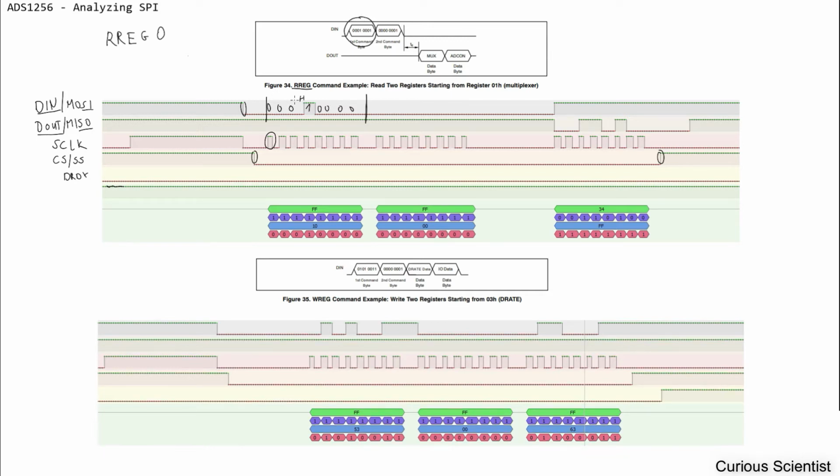Immediately I suggest that we should study this. What we have here is basically 0, 0, 0, 1, 0, 0, 0, 0. What this means is, maybe a bad example, but we have the read register command, and then we also have the 0 included, because when you send the first command byte, that contains not only the command itself, but also the value for the register address.